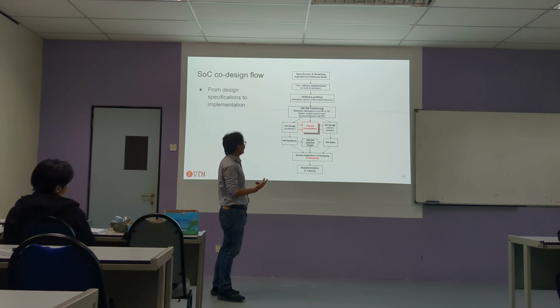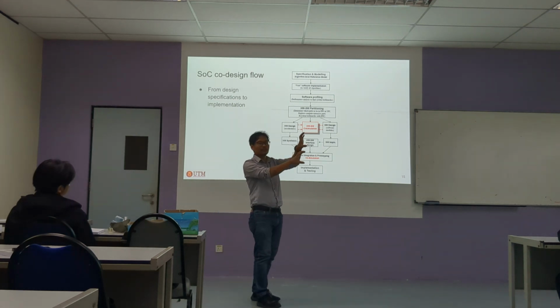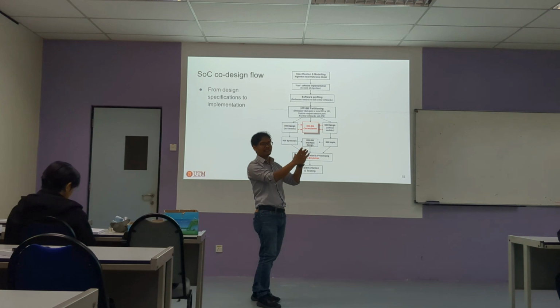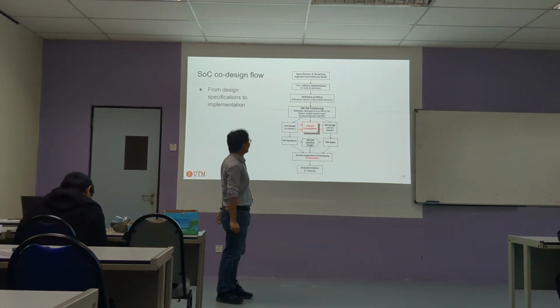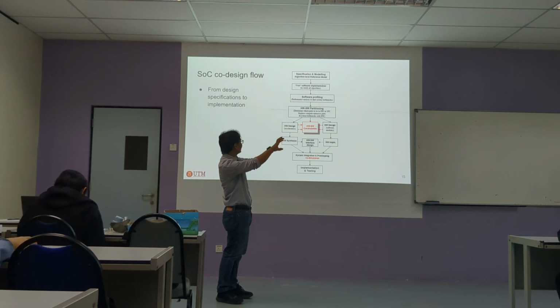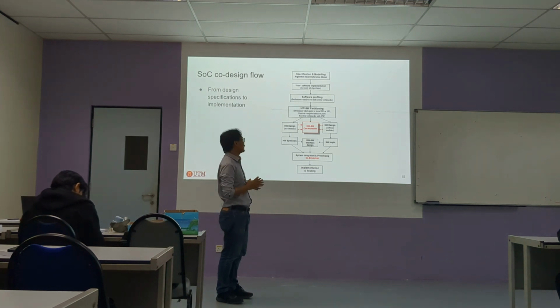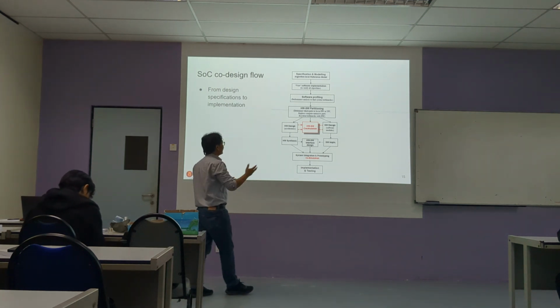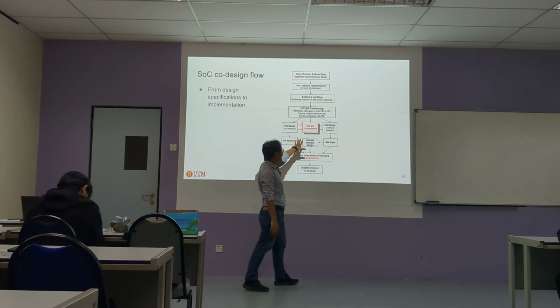Then you profile your software performance, step number 3 there. Which part of the software is slow? That is a bottleneck, right? Or something that you can make parallel. That part is the part you take and try to implement on the hardware side, on the FPGA or a custom chip. And the rest can go on software. So we break up the design.